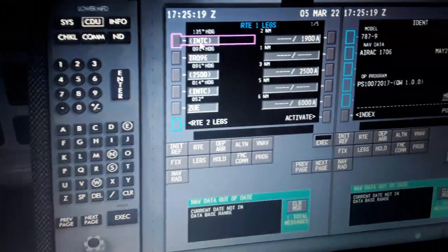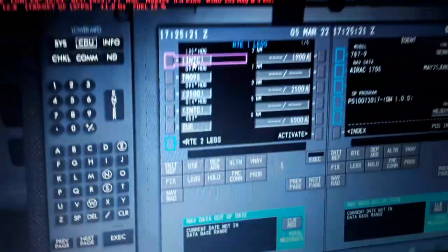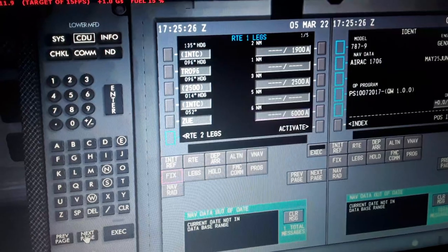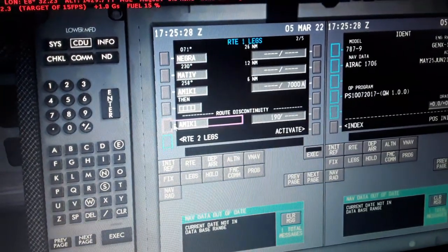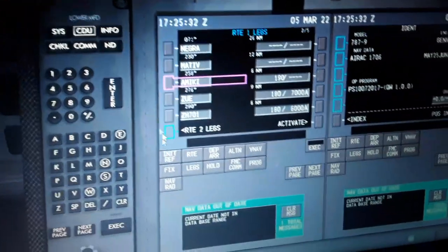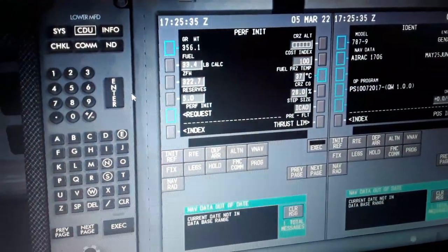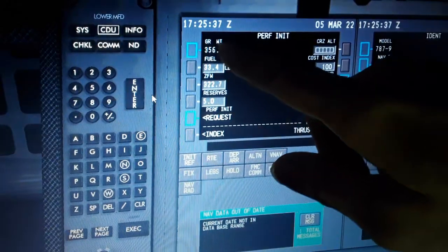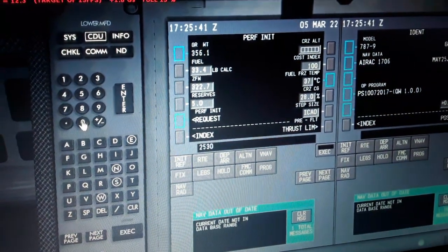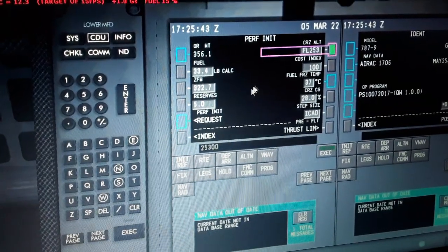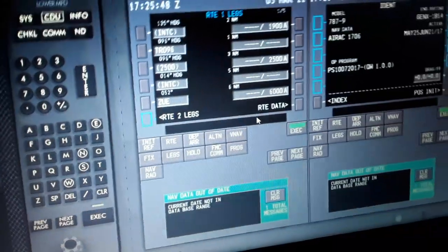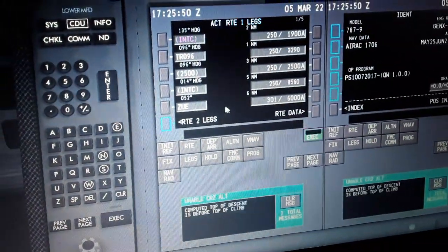So we have the first waypoint, the autopilot will follow later in flight. The flight plan: ZUE, climb to ZUE, make left turn over here, climb to the NIGRA, then AMIKI, descend, approach and landing through the Zurich 701. So we set the reserve fuel on board and gross weight for takeoff, the cruising altitude, and we activate the flight plan. So we press this green switch, the execute, that is displayed now. We will activate the route, the flight plan of the aircraft.